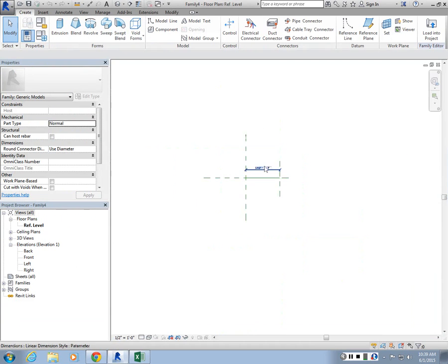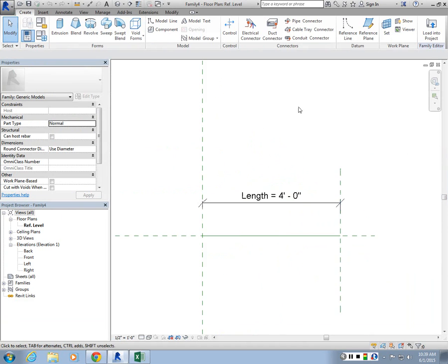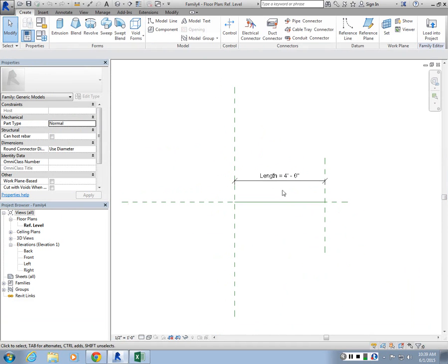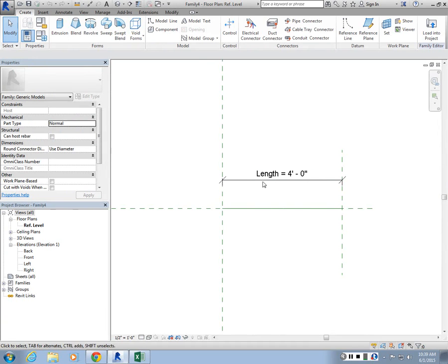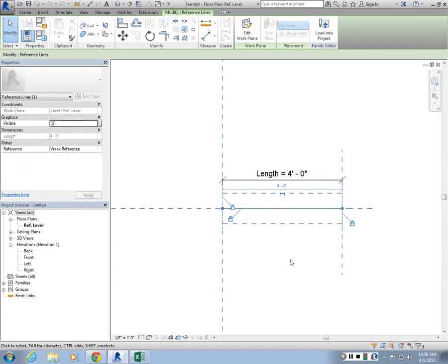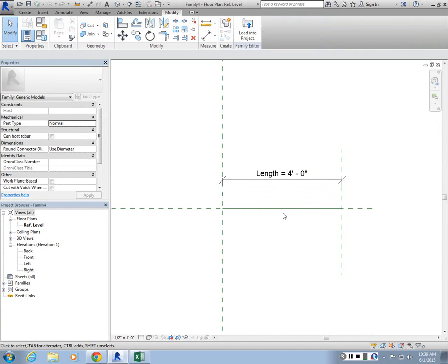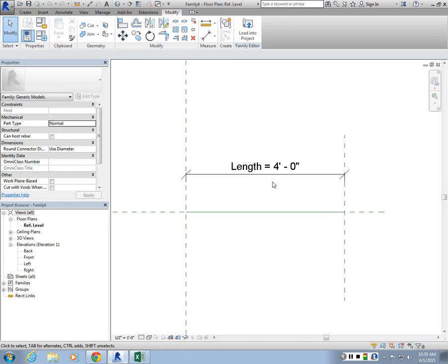And there's something special about this family, which is it already comes in with its built-in parameter, which is this length. And this line defines the length of the component, right? So I'm going to basically bring in my sweep here and lock it to one of these axes and use this parameter to feed into the width parameter we defined for that sweep, right? So I'm going to link those two parameters to each other.